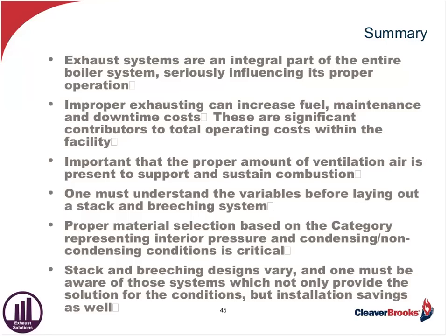If you've got a ceiling that is 7 feet or lower, you divide that by 250, and that will give you the cross-sectional area that you need to properly vent that boiler room. If the ceiling is higher than 7 feet, then you divide by 500. So you take that 3,000 divided by 500, and that would give you the cross-sectional area for ventilation and combustion air.